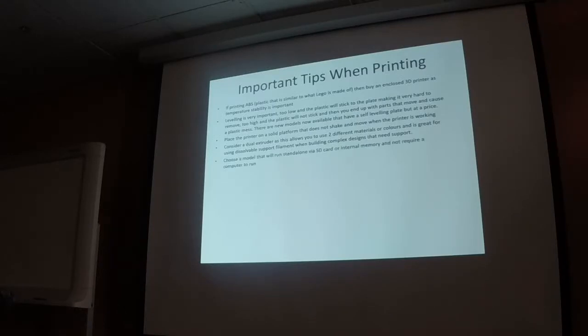So again, I said consider a dual extruder. It allows two different materials or colours, and is great for using dissolvable support filament. Choose a model that will run standalone via SD card or internal memory and not require a computer to run. A lot of the DIY kits and earlier versions required being hooked up to the computer permanently, so if your computer shut down or anything like that, then your print was lost. A lot of the new versions now are coming with internal memory or SD cards, like what I've got. So basically it becomes a standalone kind of thing.